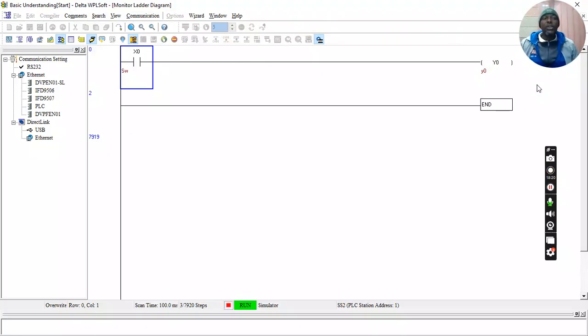All right. So this is okay with toggle switches. A switch that you can just put on, let the job happen. Remember, Y0 can be anything. That could be a machine, that could be whatever. It depends on what you wire on that output. It could be a light. Whatever you wire to that output would have been energized when Y0 went green there.